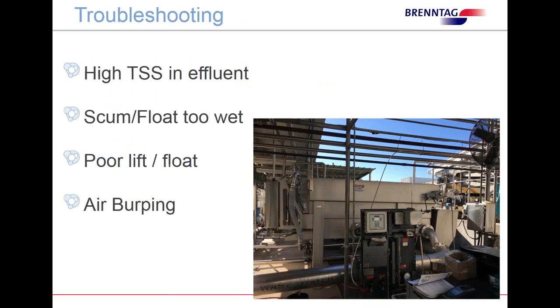So let's troubleshoot some of these problems that we potentially could see. High TSS in the effluent, scum or float being too wet, poor lift or float, or air burping. We'll go through each one of these.